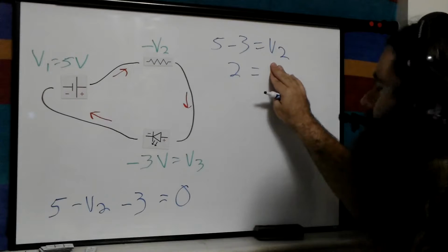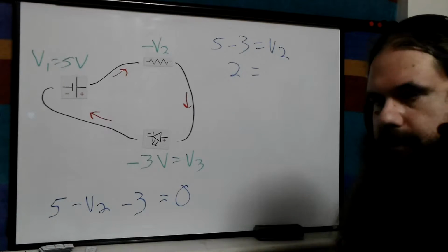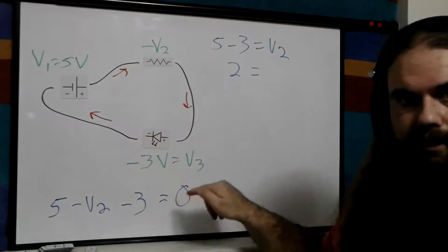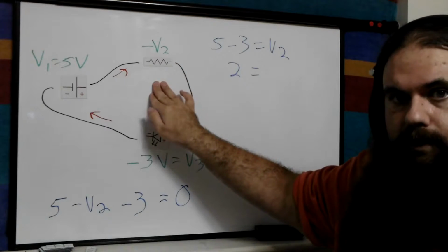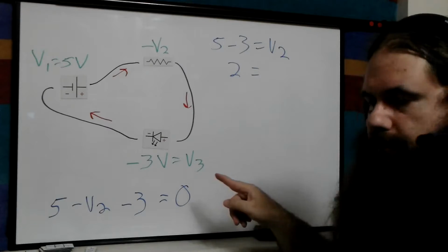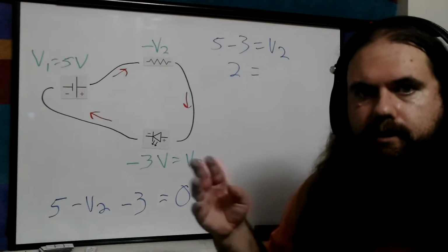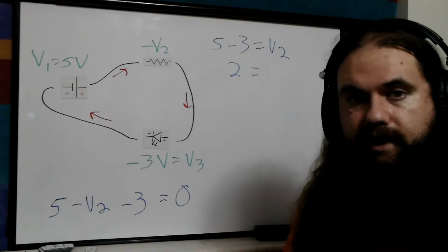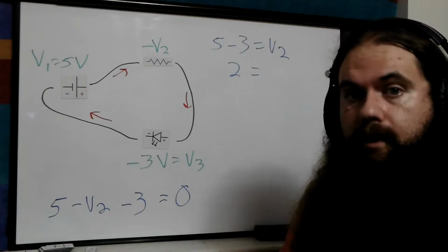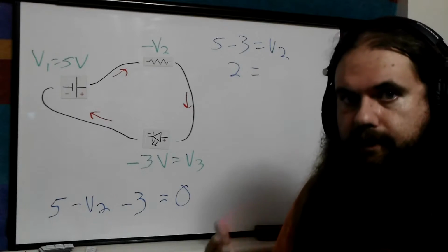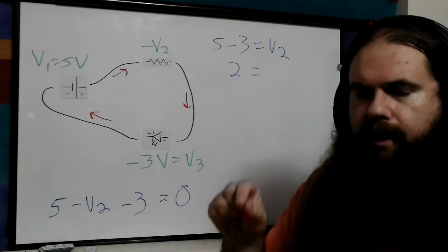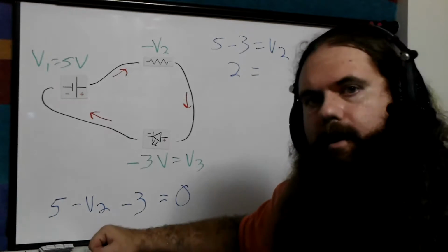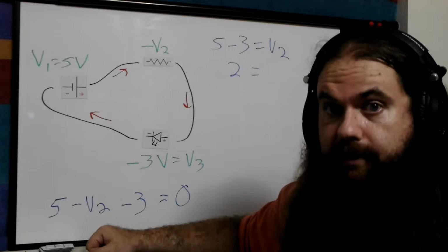It's all simple algebra. So that is how you can use the voltage law to figure out voltages you don't know. Draw a loop including voltages you know or can calculate and the one you need to figure out, and then do your algebra. Now, if you have a huge, crazy circuit and all kinds of voltages and currents and stuff, then you have to do matrices and linear algebra and so forth. Or you don't actually have to do that. That's just the good way to do it. You can also do it the slow way by hand very, very painstakingly. A much better idea is to find an online or commercial circuit simulator and just use that.